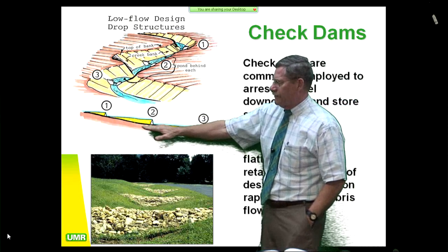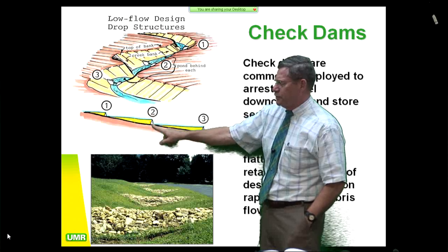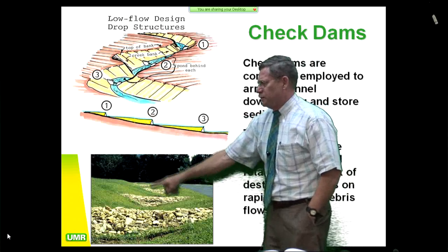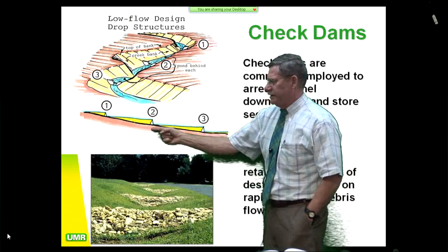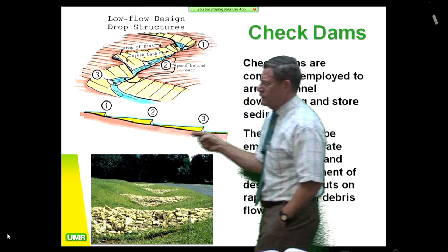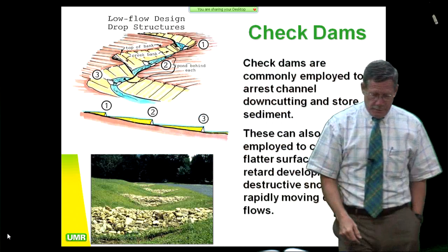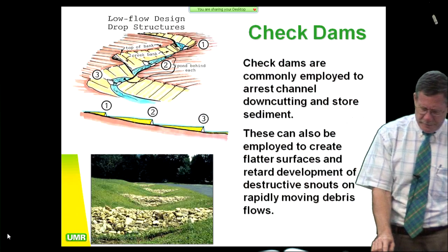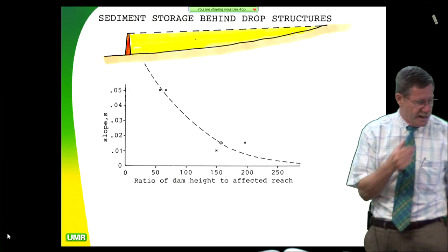You have to have one heck of a good splash pad right there where it's pouring over, or these things won't work. So they're only as good as the bed scour protection at the base of each one of the check dams. But that does prevent the snout from forming and getting as high.